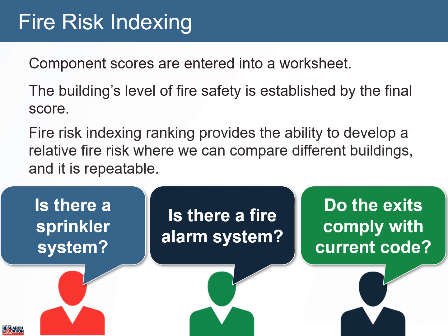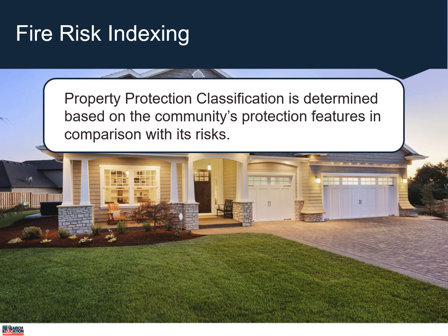Again, one of the advantages of fire risk indexing is it is repeatable. LOPA, however, is more subjective. And because different people look at some of these issues differently, it's likely that each analysis will result in a different outcome. The ranking in this fire risk indexing provides the ability to develop a relative fire risk where we can compare different buildings, and it is repeatable. Fire risk indexing is not a new concept. It has been around for a number of years, used by a number of industries.